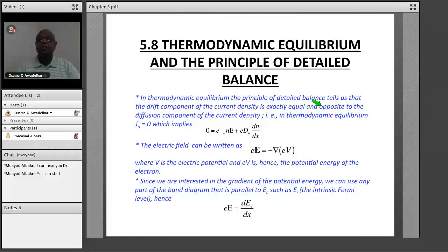There will be some motion of charge carriers at the beginning, but immediately this motion comes to zero because we reach equilibrium. This motion at the beginning is because of diffusion. Carriers start diffusing from one place to another and move randomly. After a very short time, everything is settled and we reach equilibrium. When we reach equilibrium, the total current density is zero.